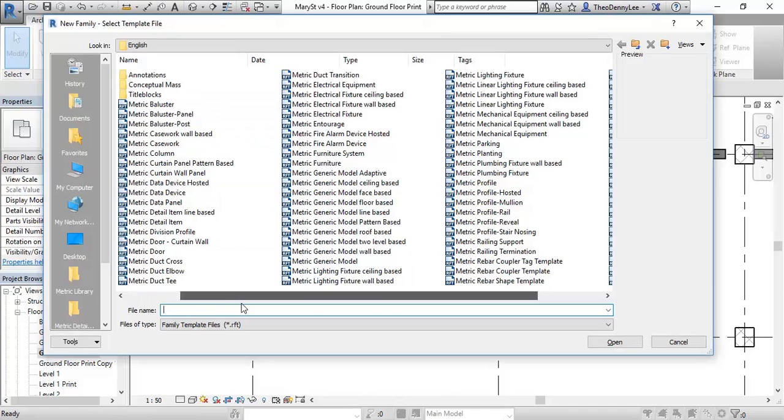And these are actually really important things in Revit, because a lot of the tools that you need in Revit are only accessible via these templates. So, for example, lighting. You only get the option to set and control certain lighting parameters by using the lighting template. So it's one of those secrets in Revit. Some of the tools are actually hard-coded into these templates, essentially.